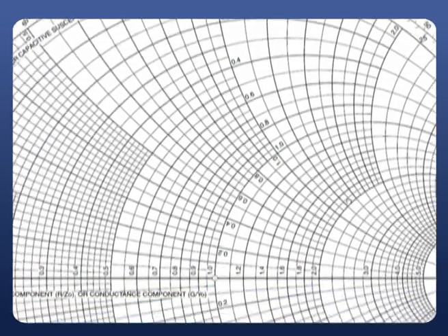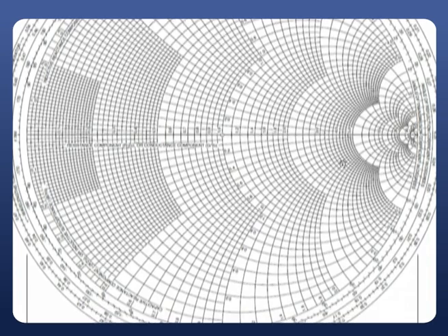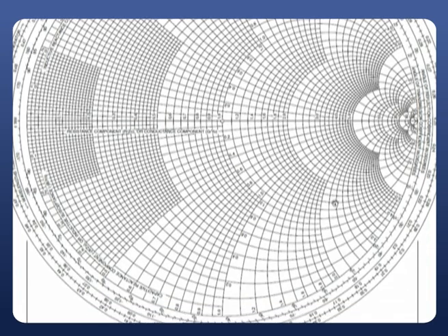Similarly, I will give you one more example with negative reactance, and with that one I will conclude how to represent an impedance. Let us consider one more impedance as 50 minus J100 ohms, that I have to represent, with the characteristic impedance 50 ohms. Then if you normalize that one, it becomes 1 minus J2. Here the resistance circle is 1 and the reactance circle is minus 2. Clearly observe, don't take that one as plus 2, it is minus 2.